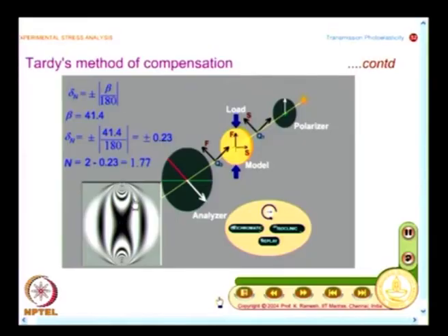I have a fringe with shape of 8. Other way of looking at it is intensity passing through the point of interest is 0. Fine. I also see semblance of fringe pattern elsewhere. When I rotate the analyzer, I see the complete model. Can you attach any physical interpretation to those fringe branches? Because I see a fringe, you cannot assign any interpretation to those points in conventional photoelasticity.